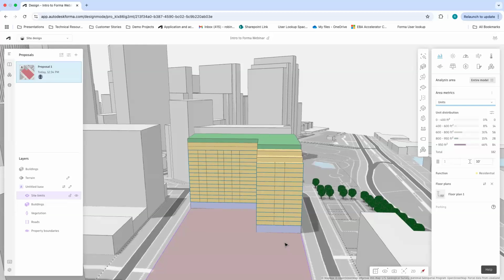Right, so just to recap here, in the past couple of minutes, I was able to draw a building from its building footprint, extrude it to a height, edit some setbacks, apply functions to the building, and then I was even able to go into the floor plan mode and start designating what would be a corridor, what would be a unit, and really start to understand the program a bit more of this building,